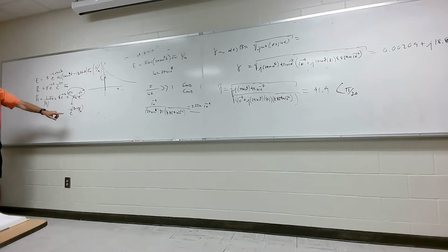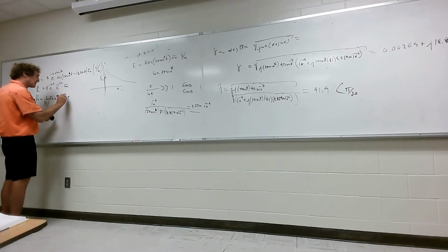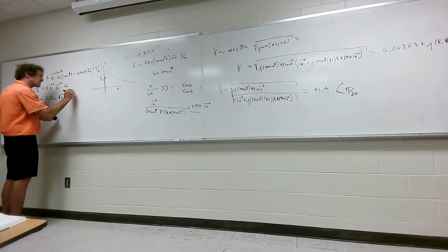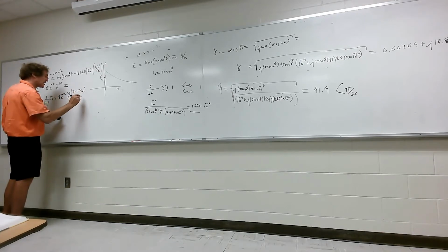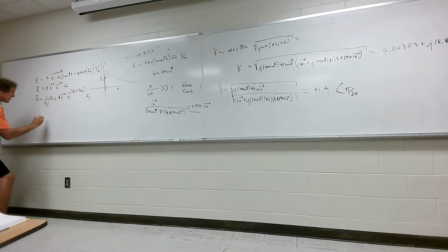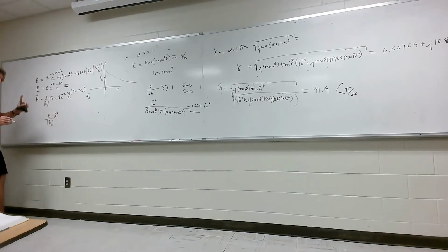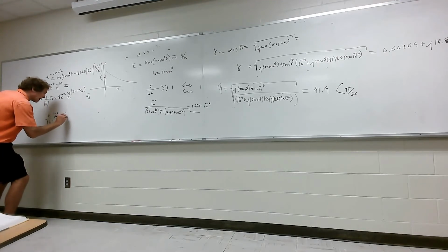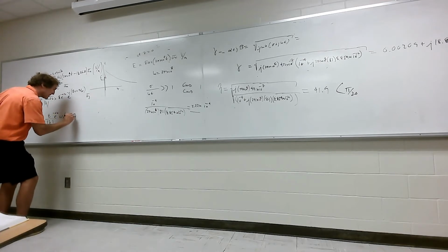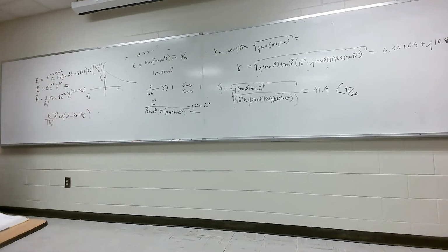But that's another story. So now I get it down to this point. You with me? Now I have, for those two terms, e to the minus j quantity beta z plus pi over 20, in the a_y direction. To go to the time domain, the only thing I'm going to do is have 8 over the magnitude of eta 1, still whatever that is, a scalar value. Then I'm going to have my e to the minus alpha z here, but then to go to the time domain, now it's cosine of omega t minus that beta z, minus pi over 20. So that's how that angle would work in there.